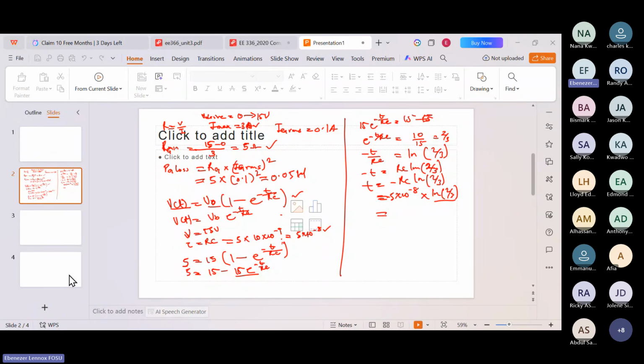Okay. So the question says we should calculate the time it takes for the gate voltage to rise up to the threshold voltage. And you know that at the gate, so this is an IGBT, right? And there is a gate. So this forms some capacitance, and the value was given as 10 nanofarad. So you realize that...